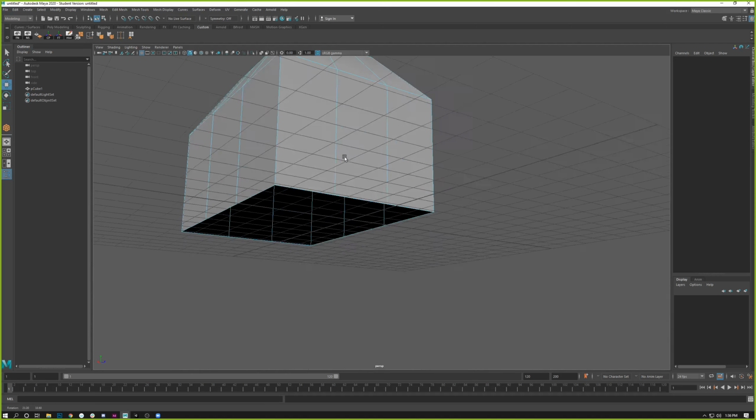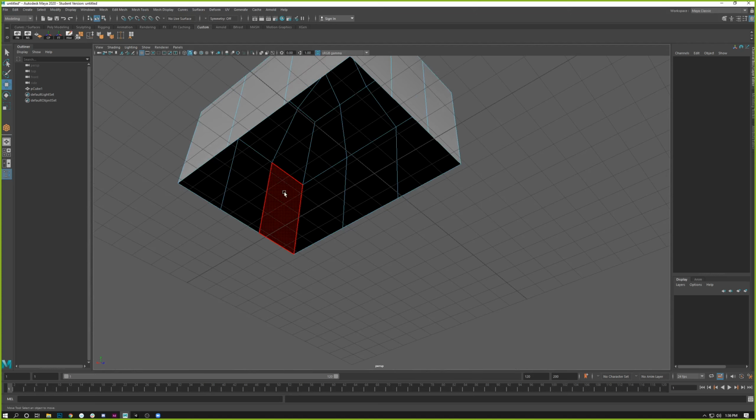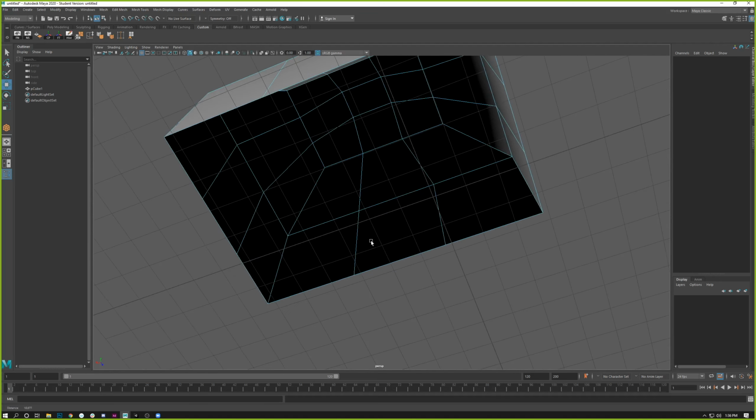Not to get too technical, but objects have something called normals, meaning that how the 3D renders something, it generally renders one side. Yes, we can make it render both sides, but then it's twice as expensive. So by default, objects only render one side out. And honestly, I think it will render fine in Maya. I'd have to test it and remember, but in a game engine, this would be transparent by default. You can make things render both sides.